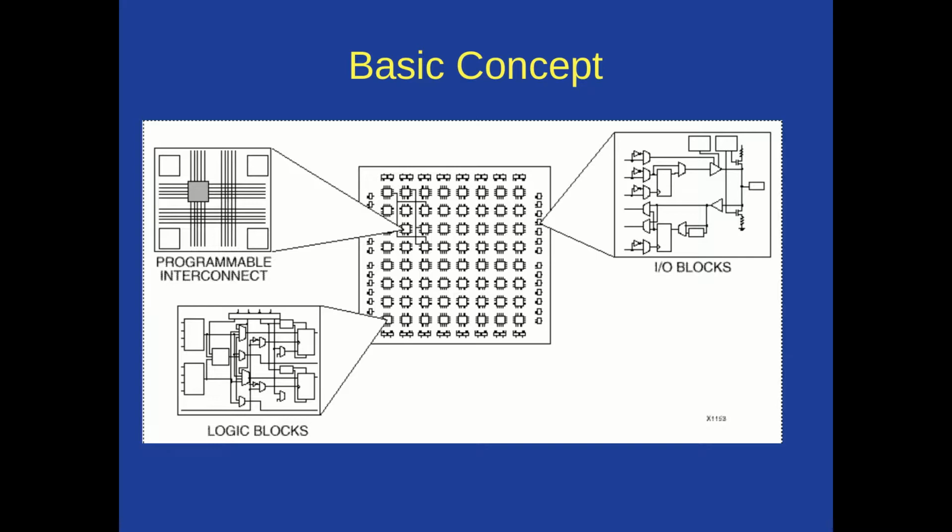Or I want you to take 3 inputs and add them together as bits and give me the sum and the carry out. So you have these programmable devices, and then scattered throughout these, you have these little interconnection matrices. So you can say, okay, take the output of this and connect it to the input of this. And so you can build your circuitry basically, but you do it all through software. And then there's I/O blocks for actually taking the signals in here and sending them to and from the outside world. And that's the essential idea of all of these devices.